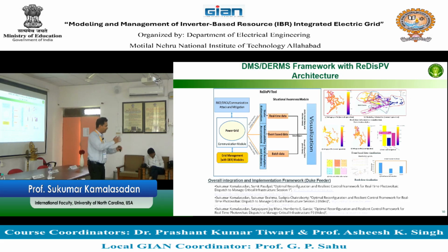So now I flip it back. I look at where is the power exchange. At the point where there is no power exchange, I take them and make groups with respect to time. They're fictitious groups. There's no control there. And that group I color code and I say, okay, 20 of them can work together. That will make the power balance. Then I send the signal to the battery, group of batteries or whatever, to control so that the power is balanced. And I continuously do that every 5 minutes, every 10 minutes, depending upon whenever you want to do in your system.